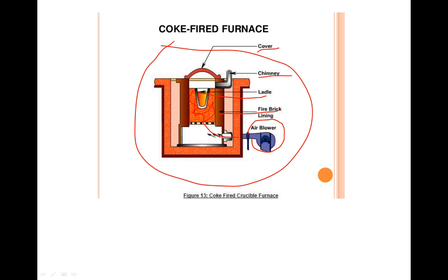In some furnaces oil is fired here in order to increase the heat and heat the crucible, and this metal is converted into molten form. Remove this cover after it reaches a certain temperature and pour it into the previously prepared mold cavity.